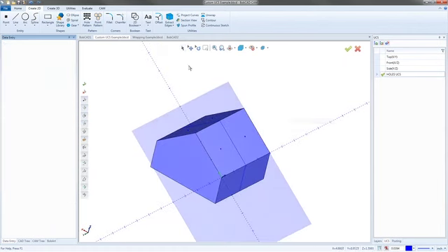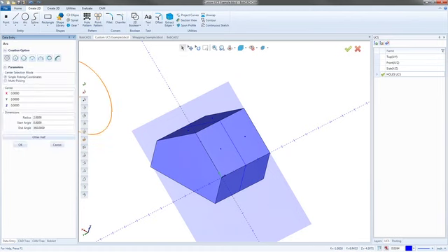There's a few functions in here, and we're going to look at a couple of them today, like translate and rotate. You no longer have to confirm the geometry after you pick it. You just pick the geometry and tell it either the movement for the translate or the rotation angle. And I still catch myself hitting the OK button all the time when I don't need to. So just be careful. Just play around with it. When you miss a step, you'll probably pick it up pretty quick.